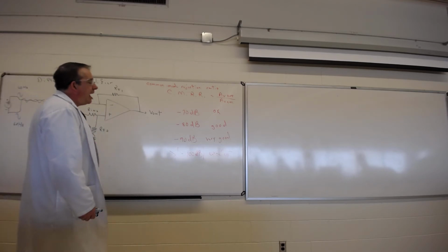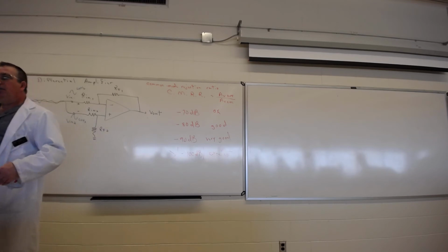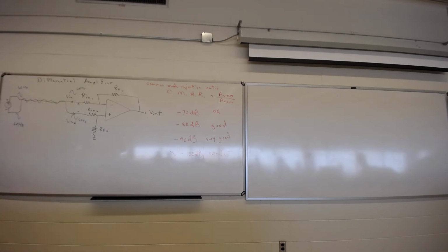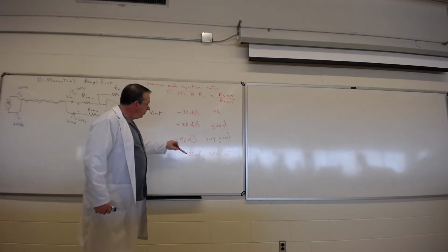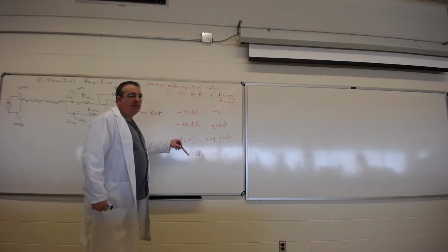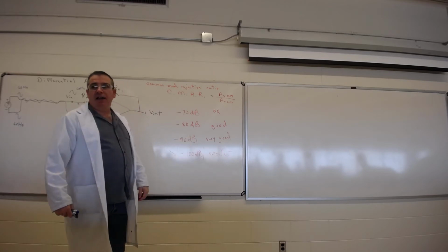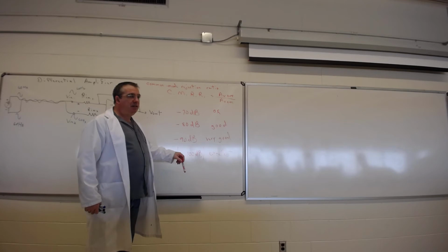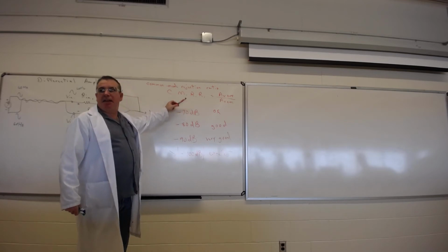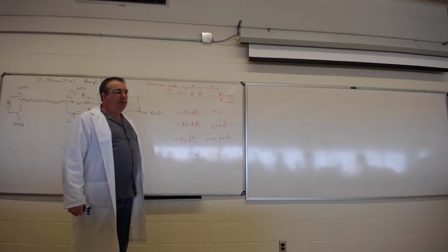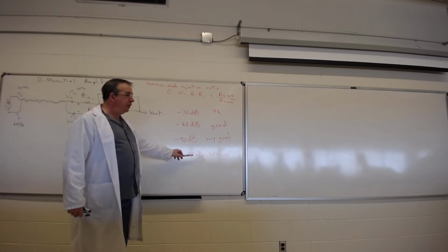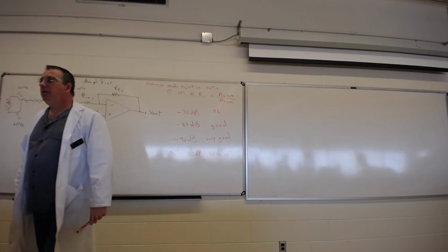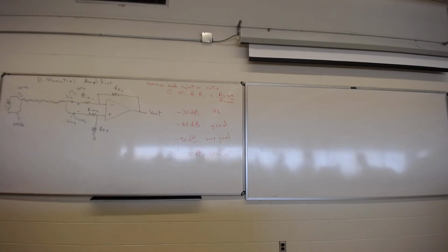So if you're looking at any kind of differential amplifier, one thing you might want to look at is what does it say for common mode rejection ratio? The bigger this number is, going towards negatives, I should say smaller, the better it is. Like minus 70 dB, that's to be expected. That's normal. That's your cheap stuff. But as you get down here, this is where you start paying your money. It gives you excellent rejection.